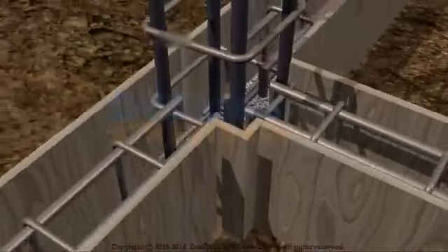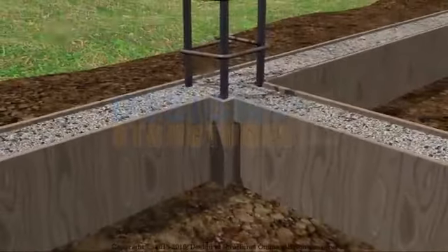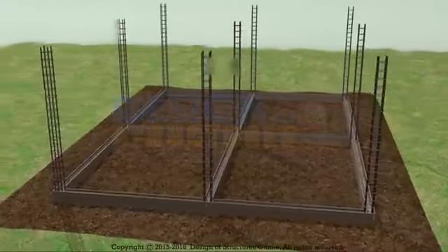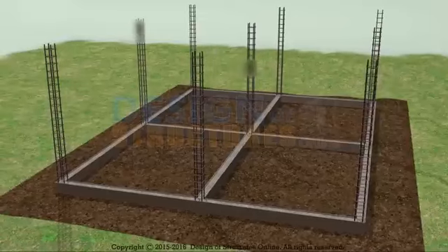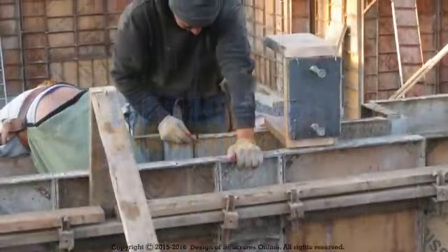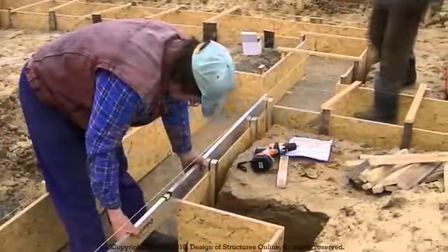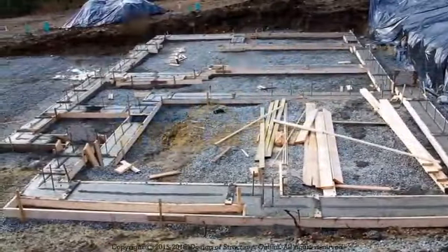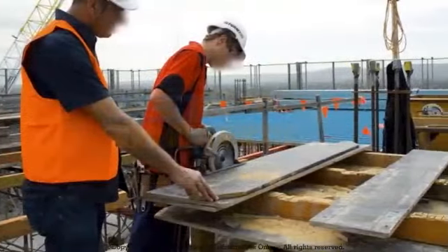Beam concreting. Beam is poured with concrete of the grade mentioned in the drawings. The positioning of reinforcement should be properly aligned. Shuttering parts and connections should be arranged in a way that makes formwork removal easy and simple, prevents damage to concrete and formwork panels so that it can be reused without extensive repair.